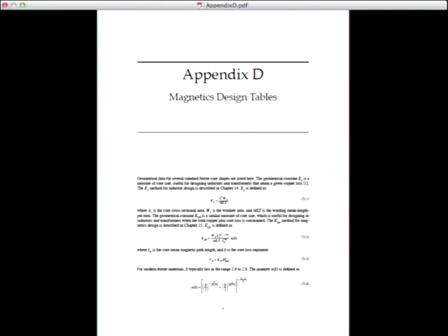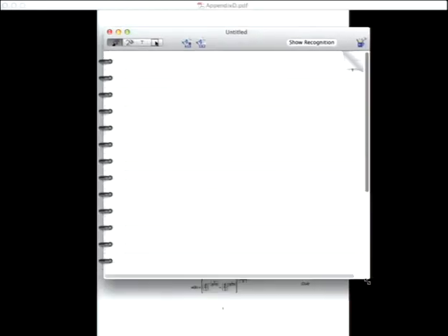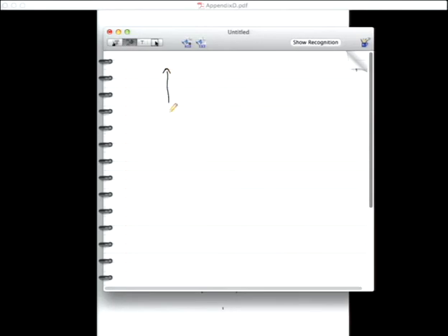So Figure 13.20 has a plot of PFE, the core loss, versus delta B for different switching frequencies. What it actually has is PFE, the core loss, which is the sum of the hysteresis and eddy current loss, and it's per unit volume.